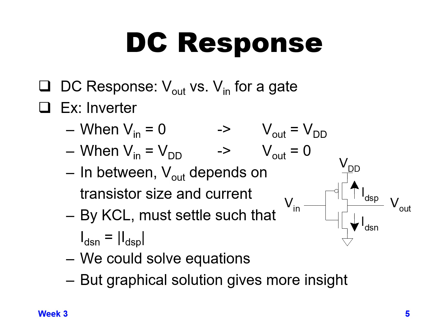So we will pull the output value to VDD, and conversely, when Vin is VDD, the output value will be 0, as long as we give enough time to get all the way to VDD or 0. If, on the other hand, our input voltage Vin is somewhere between 0 and VDD, then Vout will now depend